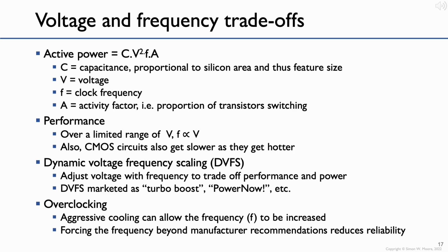So we have this notion of dynamic voltage frequency scaling, DVFS as we call it in the industry, where we adjust the voltage with frequency to perform that trade-off. DVFS is often marketed as things like Turbo Boost or PowerNow and other crazy names. Of course, this also links in with the whole idea of overclocking, where, if you've got a gaming rig, you might want to aggressively cool the system.